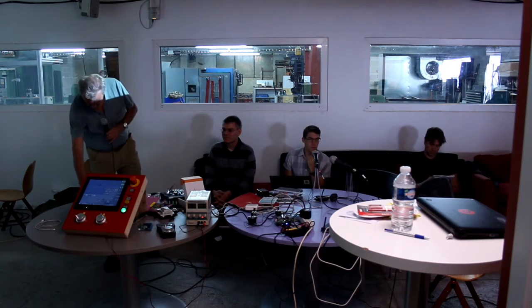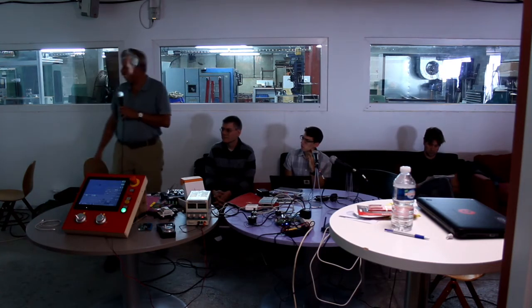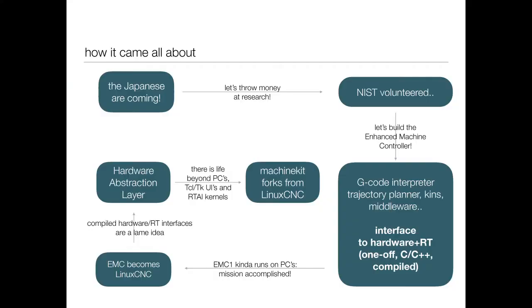Going for a research prototype, what that contained was an interpreter for the G-code language, which goes back to the 50s. Most of you will probably be familiar with it. It's a simple language to describe a trajectory of a tooltip made from lines, arcs, Bezier curves, splines and so forth, which typically describes the cutting path of a mill or any other automatically driven machine.